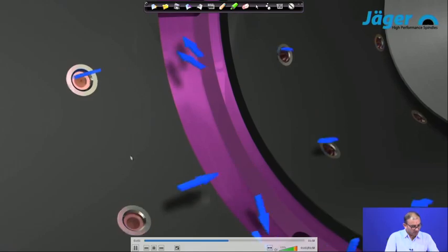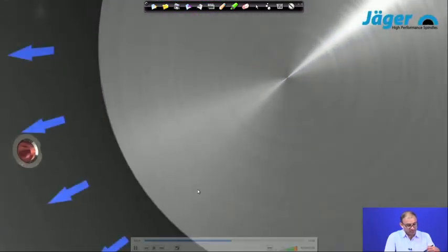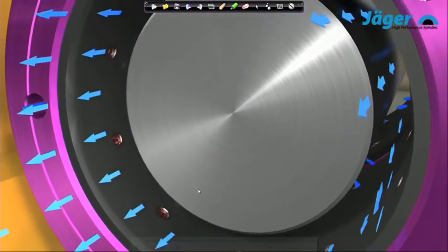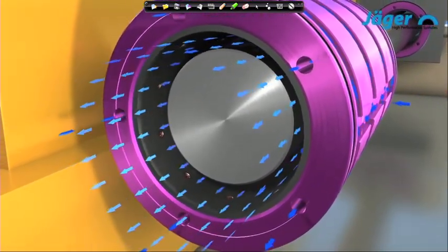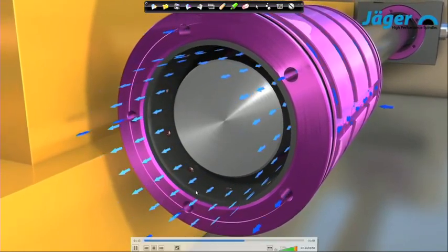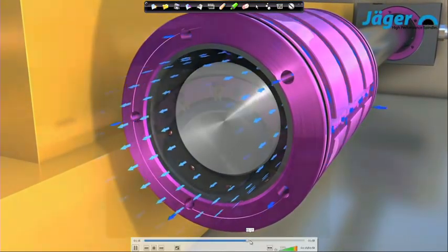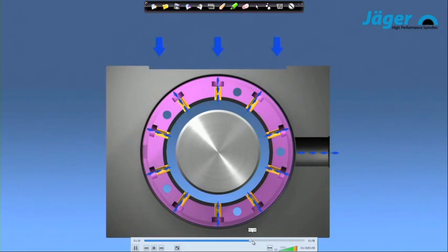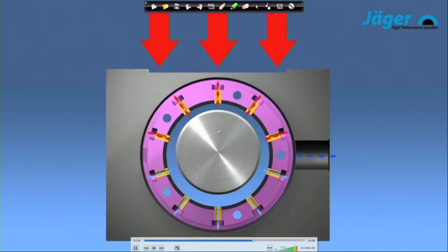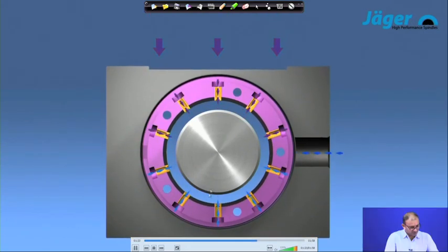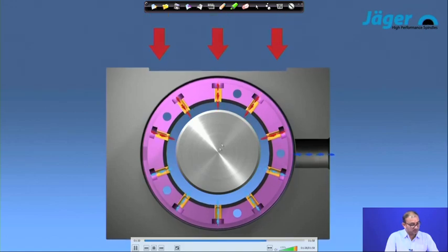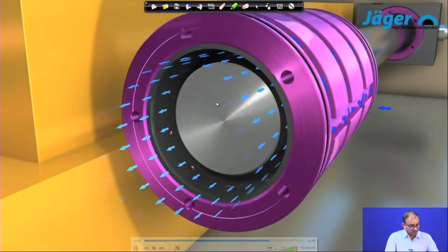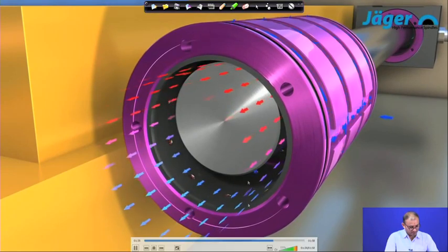And once there is no contact of this part, then you can easily move this shaft to and fro, or you can move the table to and fro, that is up to your application, which one you want to make stationary, which one is a movable component, correct. So, this is from the side view. So, now this is the way you can actually measure. So, your shaft is always at the center irrespective of the loading. So, the only thing you have to make sure is the loading is within the permissible limit of the pressure of this particular aerostatic bearing.